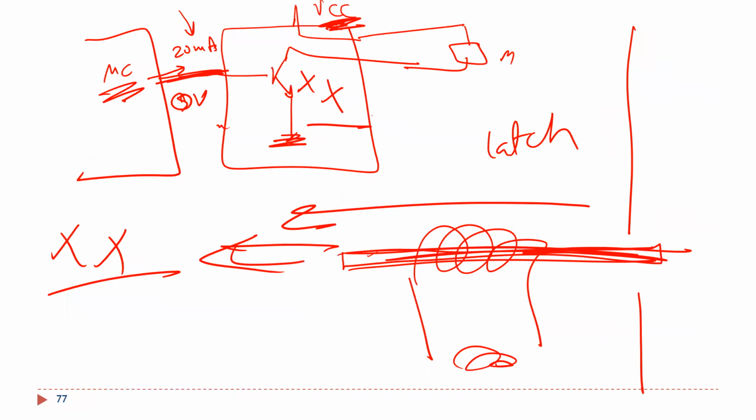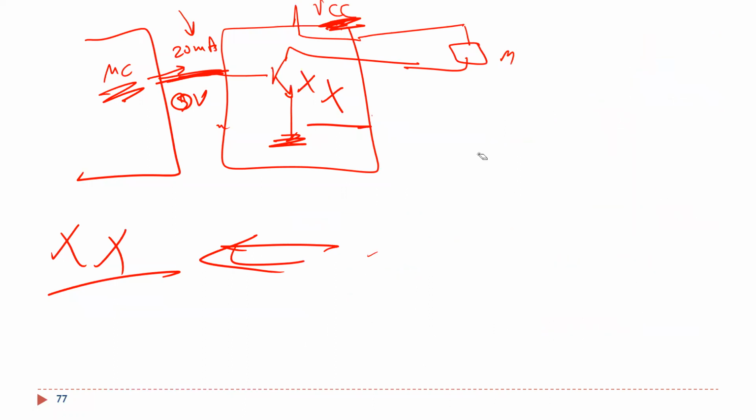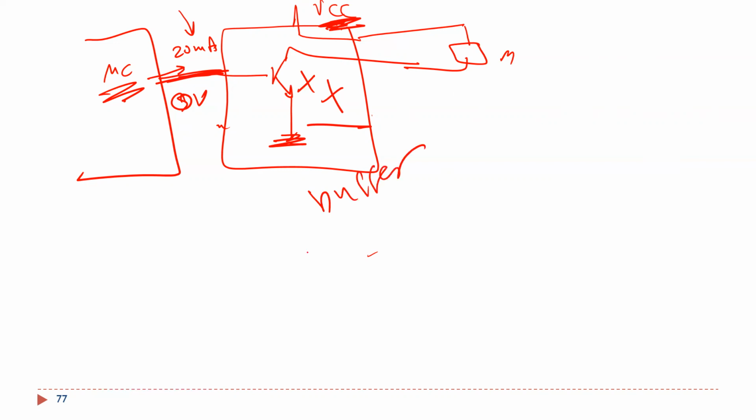Now, what I told you currently, guys: if I want to connect a motor, for example a DC motor, to the microcontroller, and the microcontroller cannot give you enough current, you have to connect a circuit here. This circuit sometimes is called a buffer. It has several names, but one of the names is just buffer. Okay, this looks nice.